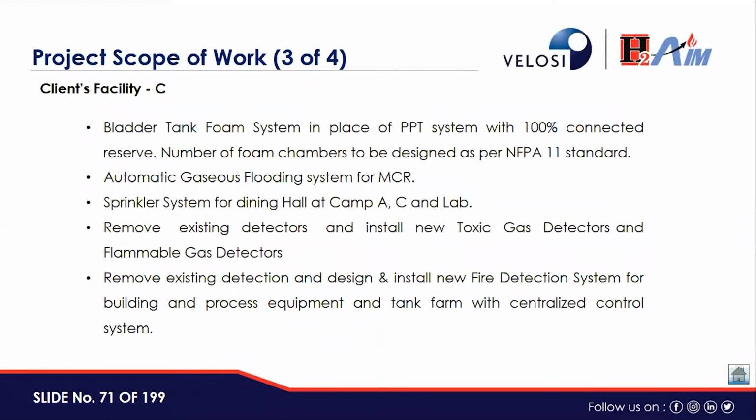Then we have to perform a study by removing the existing detectors and installing new toxic gas detectors and flammable gas detectors. And then removing the existing detection and designing and installing a new fire detection system for buildings, process equipment and tank farm with a centralized control system.